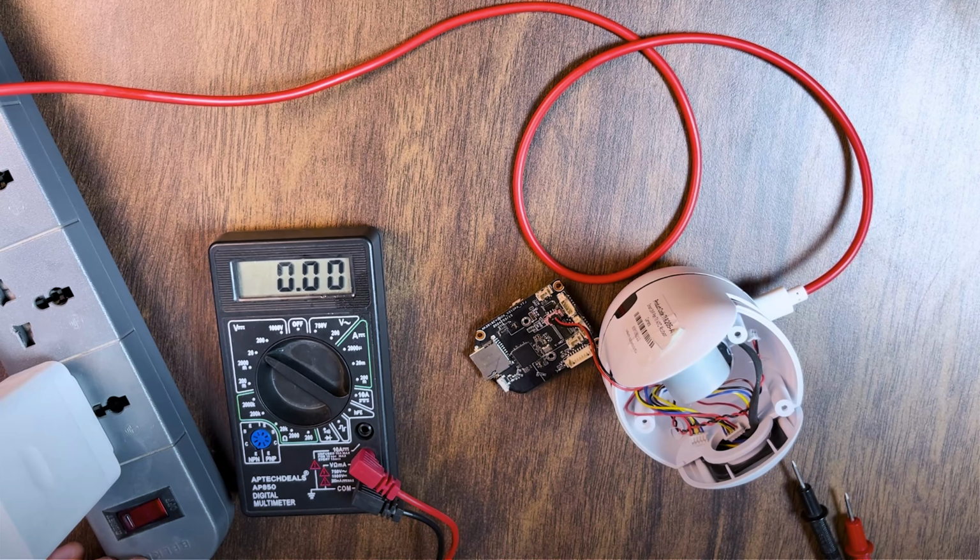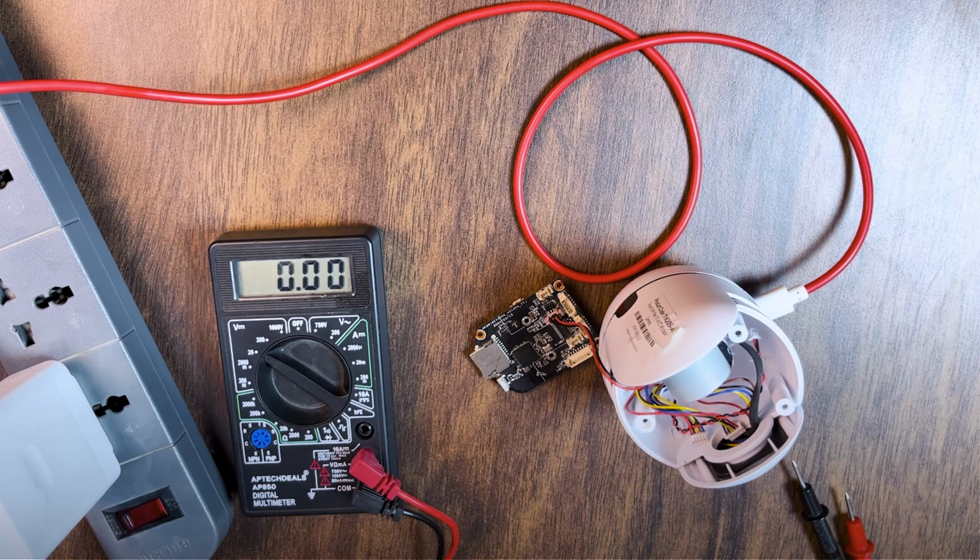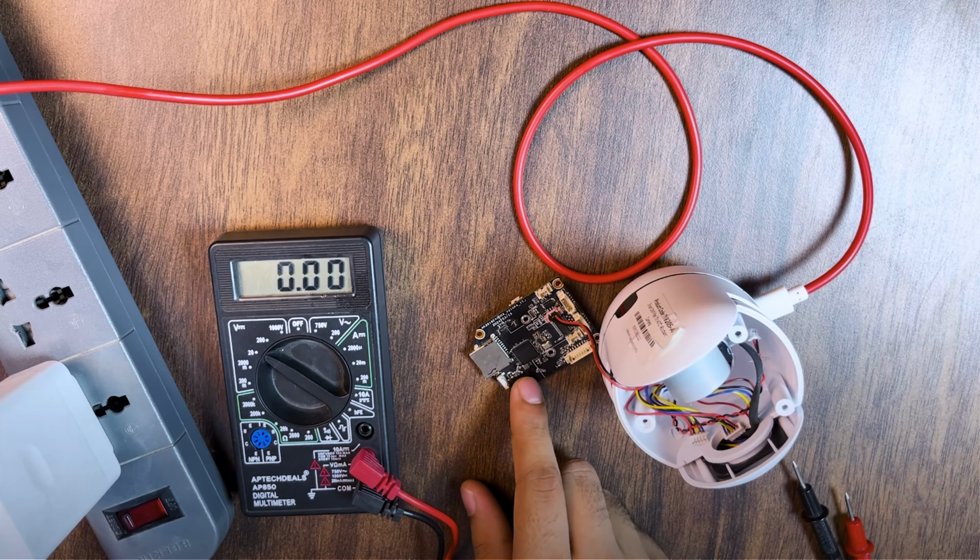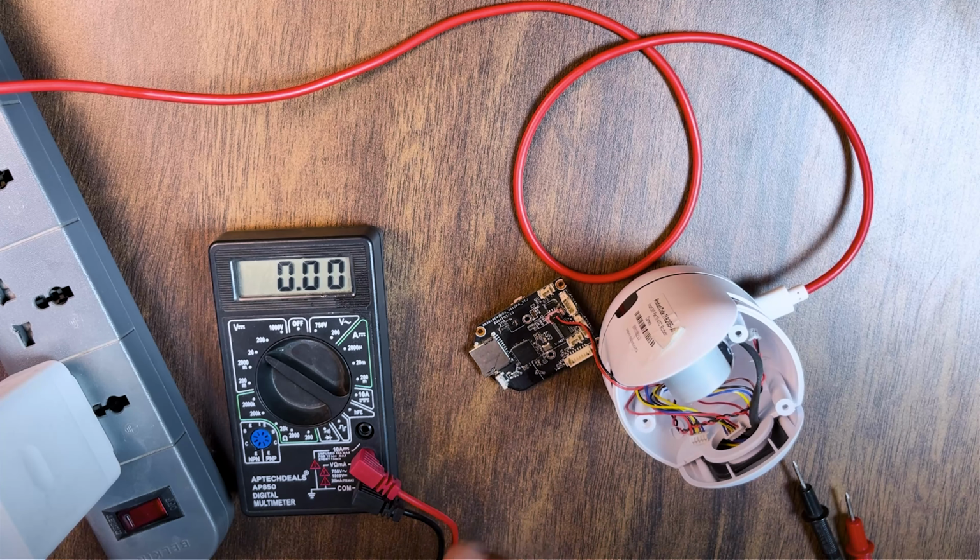Now, while you can do this method to figure out the RX and TX, what you could also do, once you figure out which is the ground port, is just connect the RX and TX lines to the TTL reader you are using, and then just see if you get any output. So you connect the RX of your motherboard to the TX of your TTL, connect it to your laptop or your PC or whatever peripheral you're using, and use whatever you're using to read that USB to UART connection.